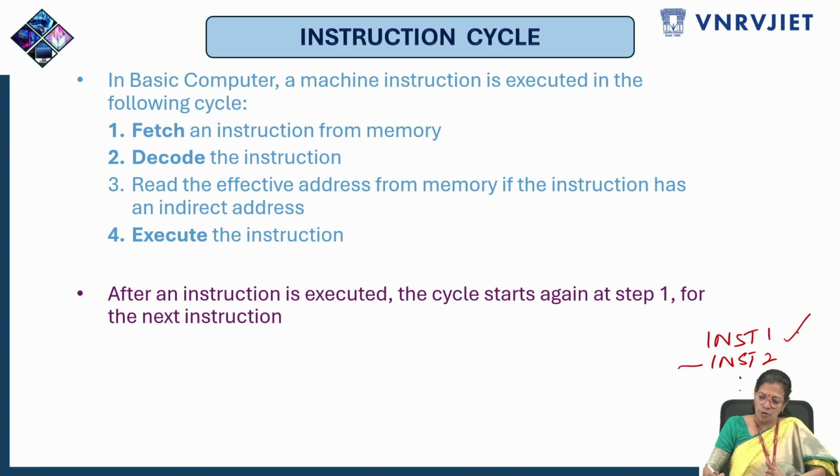So that is why the operations that are performed for every instruction will be called one cycle. So the entire instruction cycle is divided into different subsections. And of course, they also depend on the type of instruction, so they are different for different instructions. Most every instruction has to be fetched and decoded, that is for sure, and execution should also happen based on whether it is using a memory reference or not for the data.